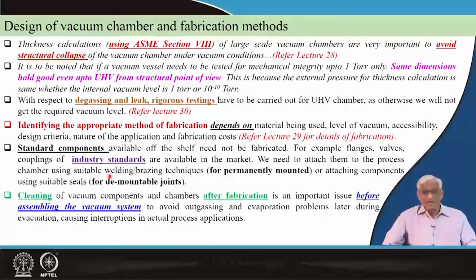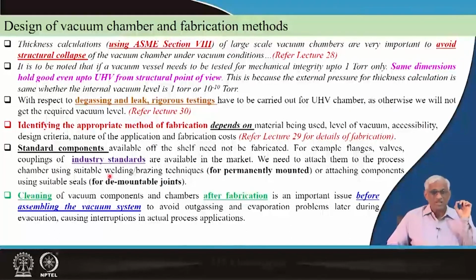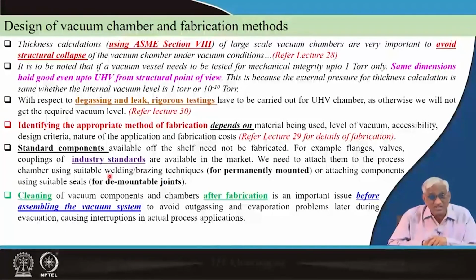Then cleaning also is a designed cleaning, whether you can use water cleaning or soap water or carbon tetrachloride or some other special cleaning agent or purging of the gas. If you are purging that gas load, who will remove it later? You have to purge, means fill it and again pump it. It takes some finite amount of time. You have to minimize that time. That is the initial preparation. That is a part of the design issue.